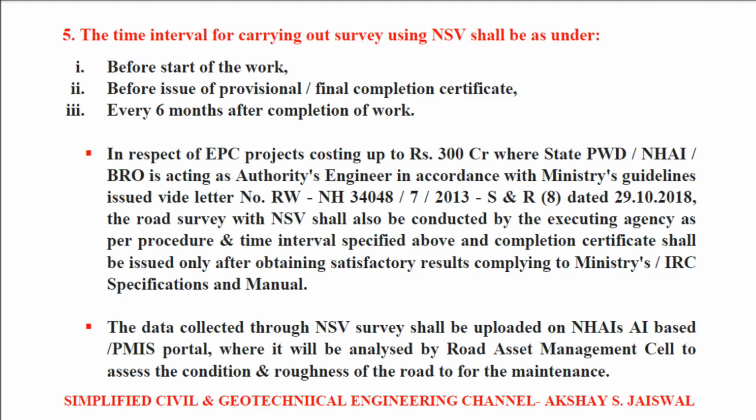In respect of EPC projects costing up to 300 crore, where State PWD or NHAI is acting as authority engineer in accordance with Ministry's guidelines issued vide letter number RWNH 34048/7/2013 dated 29 October 2018, the road survey with NSV shall also be conducted by executing agency as per procedure and time interval specified above, and completion certificate shall be issued only after obtaining satisfactory results complying to Ministry's or IRC specifications and manual.